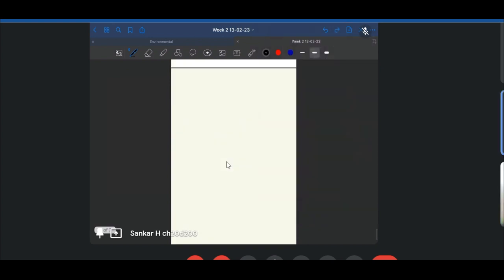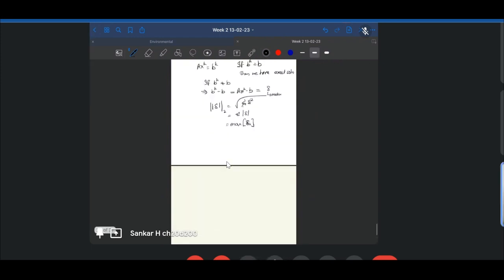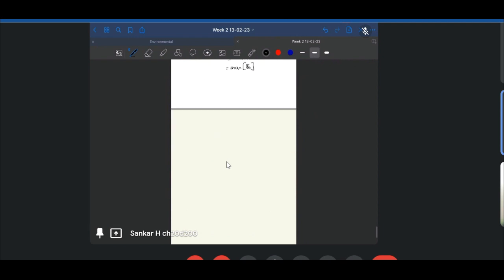It's regarding the inlet conditions for nozzles, converging and diverging sections. Mine is a theoretical doubt because I'm just not able to visualize how Mach number varies, the nature with which Mach number varies with respect to inlet Mach number. That is, if inlet Mach number is supersonic and we pass it to a converging duct, the exit Mach number is subsonic, or it is less than the inlet Mach number.